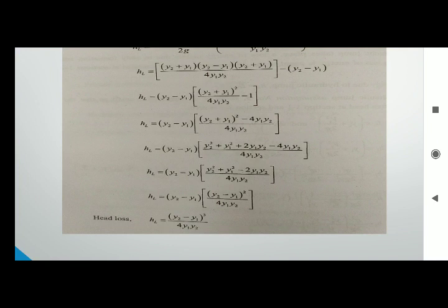In the head loss equation, we have to know both y1 and y2. For the depth of hydraulic jump equation, data at any one section is enough to calculate data at the other section. Then I can calculate the hydraulic jump. For the third unit, if problems are asked, you have to use these two formulas only. Other than that, there are no other mathematical derivations for unit 3.